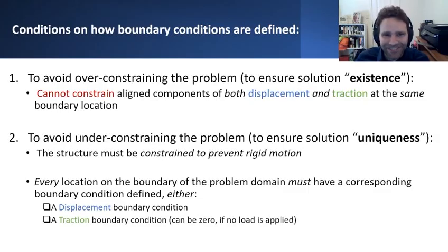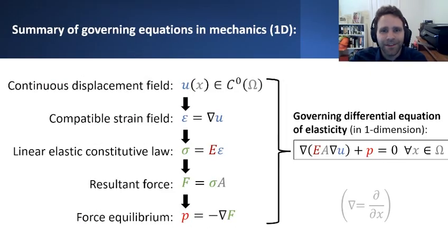If you're not sure, if it looks like it's just a free surface, then you just prescribe zero traction there, and that's probably the easiest one to deal with. But it does mean that if you're trying to set up these problems in a mathematical context, then you really should give some attention to this and just make sure that you're prescribing displacements and tractions along the entire portion of the boundary when you're defining the problem that you're setting up. Otherwise, it's kind of ambiguous. You might not necessarily know what kind of problem you're getting out of it, and hence you'd violate this condition of solution uniqueness.